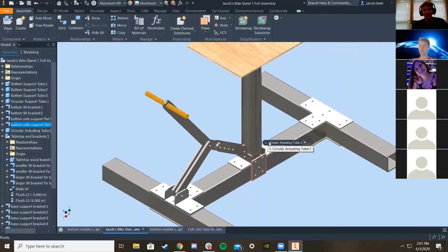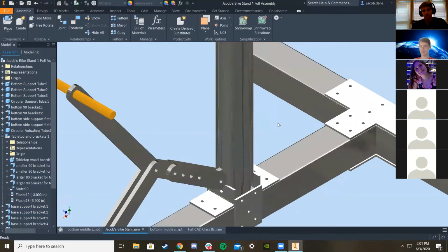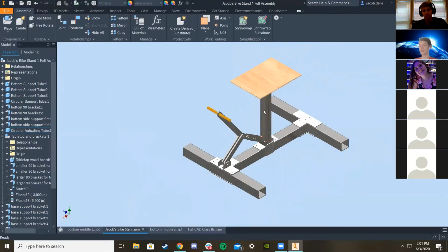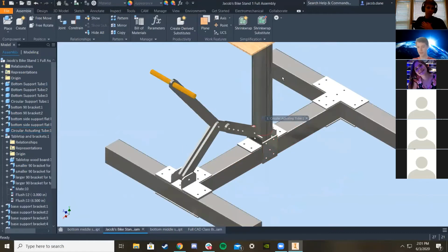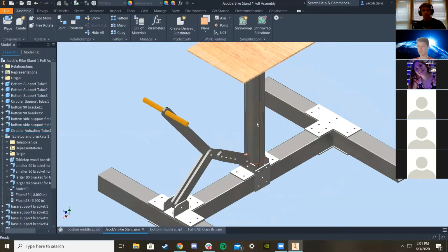So basically that makes it so it slides really well, and it doesn't wobble around when you put them on top of each other. In the real world, you can't just have them perfectly equal, because there are all these tolerances and everything. You also might put things like lubricant between the tubes to make sure they slide well. And so I'm going to put a very small difference between the tubes, but besides that, everything should be the same idea.